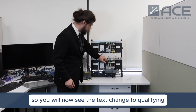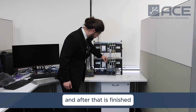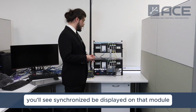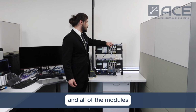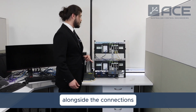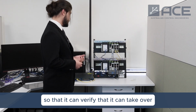So you'll now see the text change to qualifying. So that qualifying sequence is occurring, and after that has finished, you'll see synchronized be displayed on that module. And in this process, the only things that are occurring is it's testing all of the firmware in all of the modules, and it's testing that the modules are equivalent alongside the connections so that it can verify that it can take over control in that event.